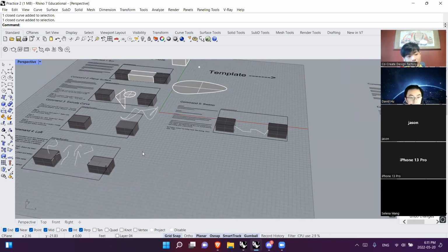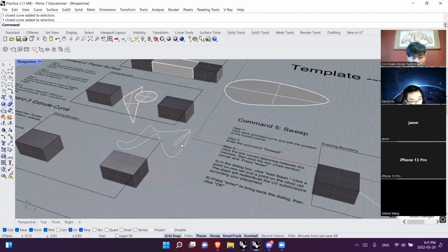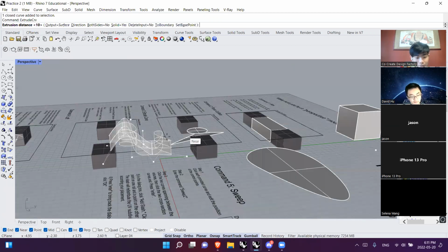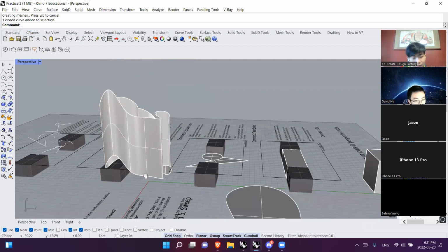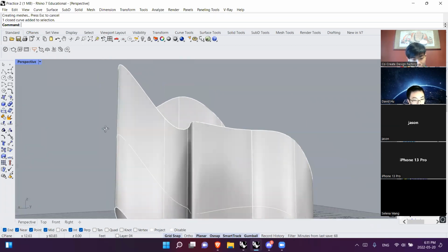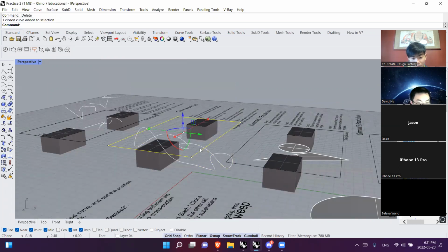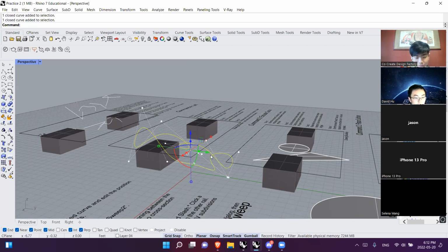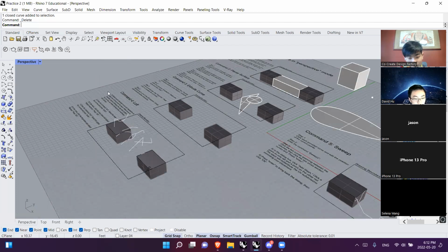It opens up a lot more possibilities. Let's go back to extrude curve for a second. When you're making a poly surface from an extrude curve, you're essentially just getting a 2D shape and moving it straight up. You don't really get any variations, see? Because your top and bottom are going to be the same. If you're looking to make something from extrude curve, it might work, but Loft is a lot more interesting.